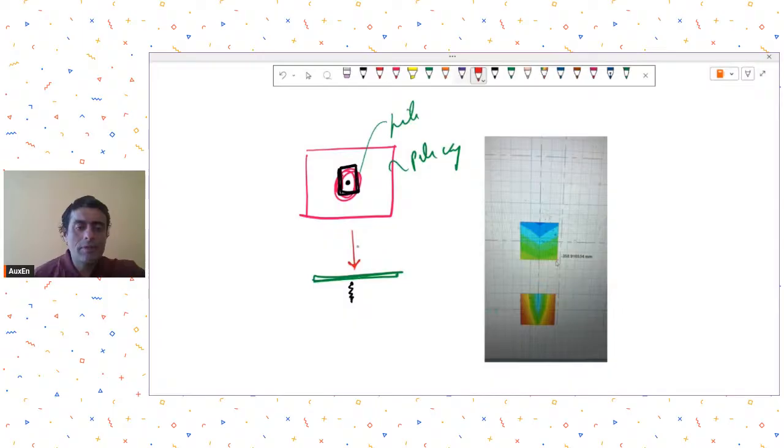So what happens in these cases is that if there is a movement in the column, there will be unrestrained deflections in your pile cap because of the software issue, that there is nothing restraining this pile cap from rotation, isn't it? You only have a single spring assigned at the pile point, and because this was a single pile cap, you only had this.